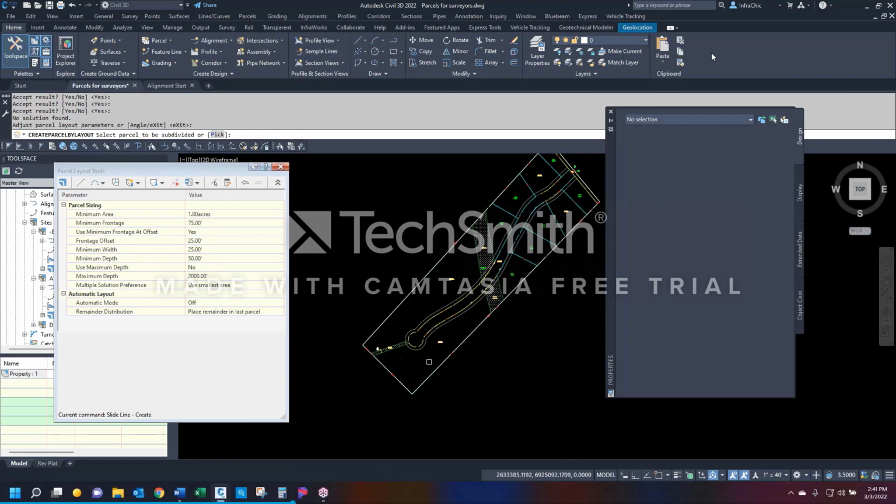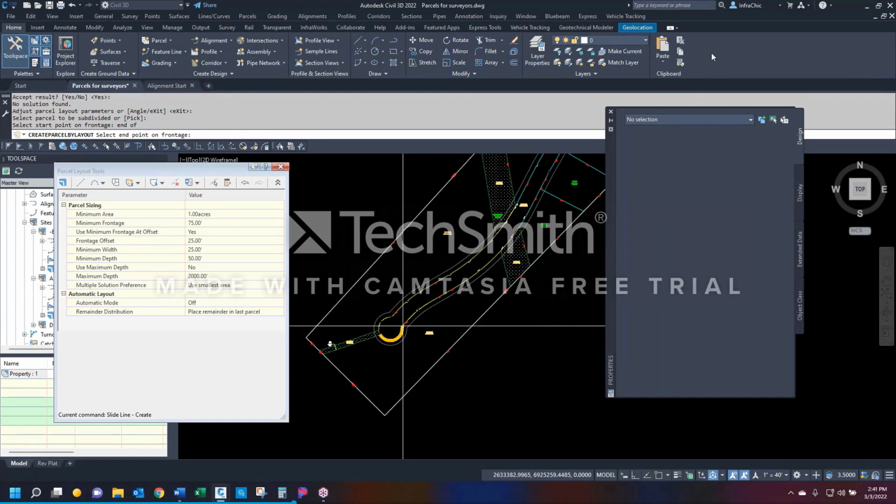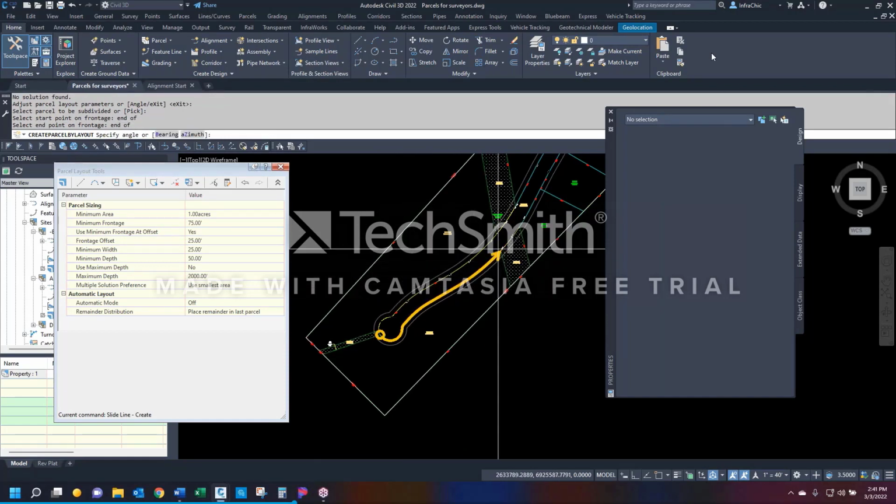Now, I turn these in. Let's start with this side down here on the bottom after the pipeline easement. Grab the label. See, it stays in it. I haven't hit escape yet. End of the 20-foot drainage easement. Jig line around the bend to the pipeline easement end. Okay, start to end, looks good. Enter, enter, enter, enter. Looking good. All right. One more enter to get it out of that.